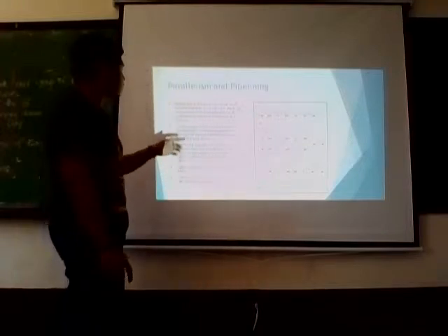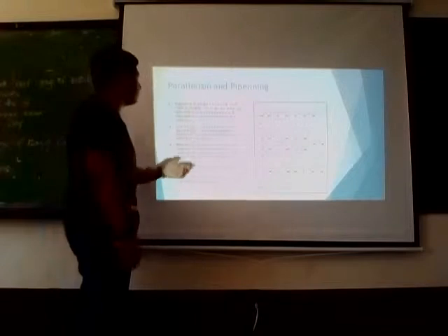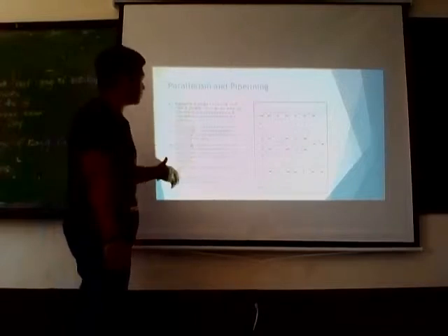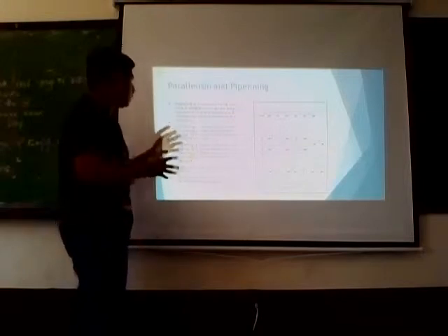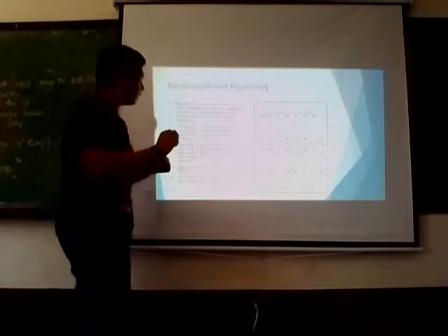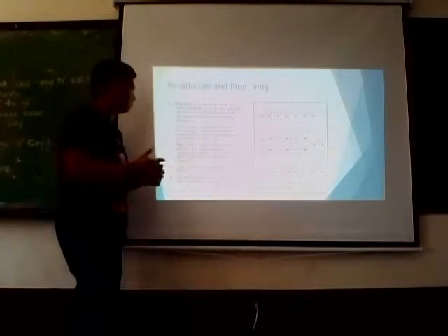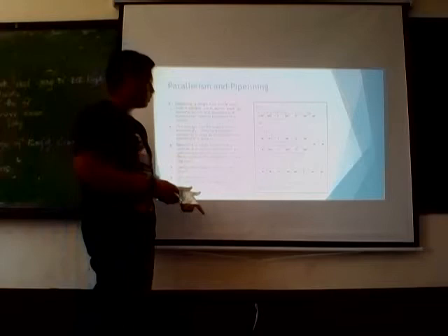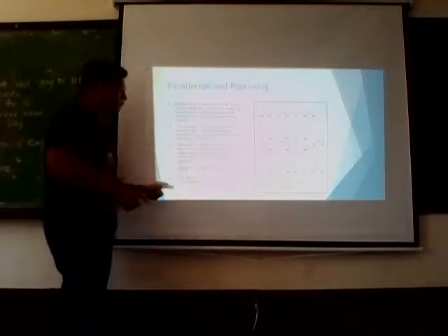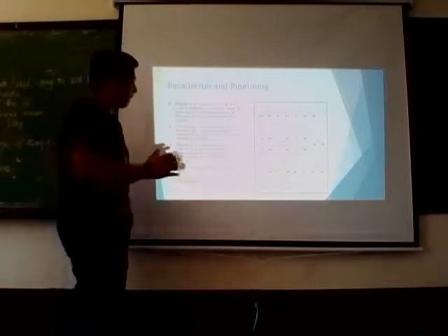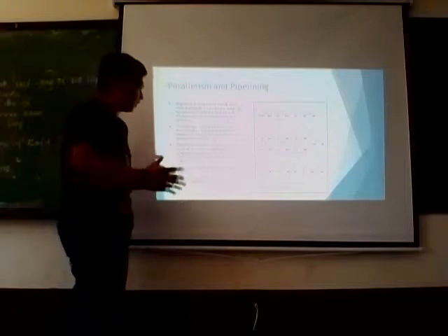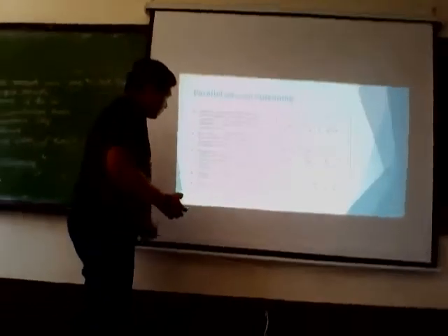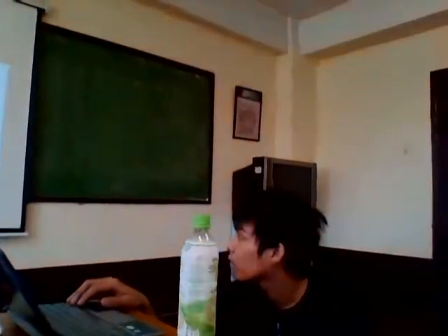Replacing a single function unit with n parallel units allows each to operate at 1/n frequency. A multiplexer selects between the results. Now, the voltage can be scaled down accordingly, offering a quadratic saving in energy at the expense of doubling the area. The next is pipelining. Replacing a single function unit with an n-stage pipeline unit also reduces the amount of logic in the clock cycle at the expense of more registers. Again, the voltage can be scaled down. The two techniques can be combined for even better efficiency.